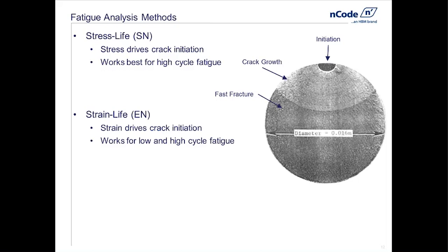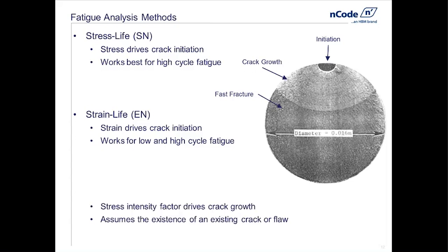Now you may say, hang on a second, stresses and strains, I learned about those. There's some letter number that relates those two. As a matter of fact, if you think hard enough, you might remember it's called the elastic modulus, or Young's modulus. And you'd say, wait a minute, aren't these doing the same thing? Stress life and strain life, wouldn't they be the same thing? We'll find out that they're not necessarily the same, because the elastic modulus is not the only thing that governs the relationship between stress and strain under all loading conditions. The last method we'll look at today is crack growth, which says we have a crack. How quickly does it grow?